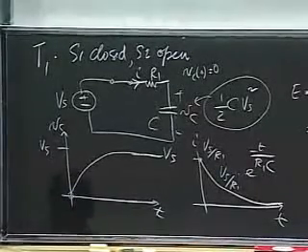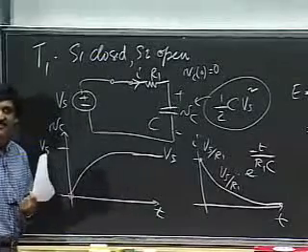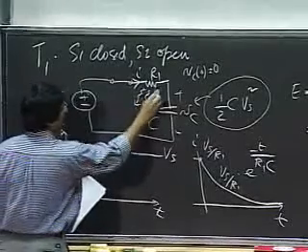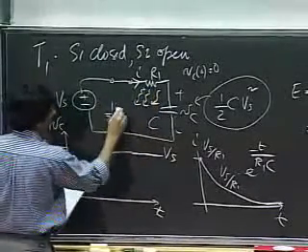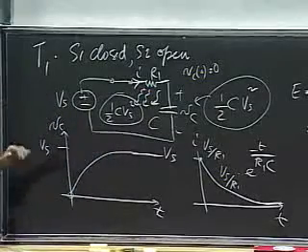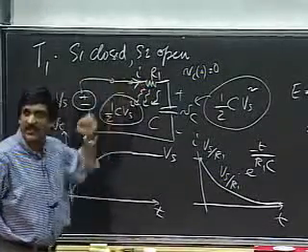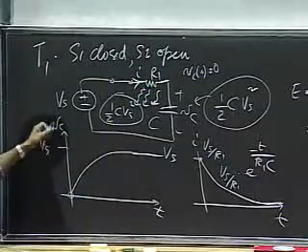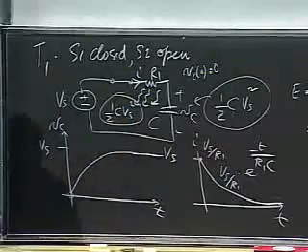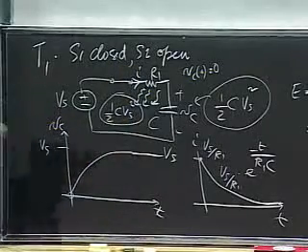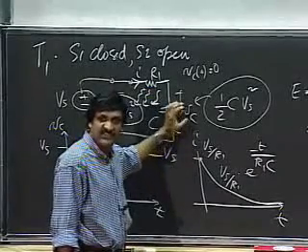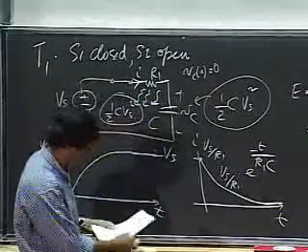So the resistor has walloped half the energy. Let me just show it to you. So dissipated half C Vs squared. It's pretty interesting. It's a pretty simple result. If T1 is very large compared to the time constant, then half the energy is on the capacitor, and half of it has been burned by R1. This energy hasn't been burned. It is simply stored by the capacitor.